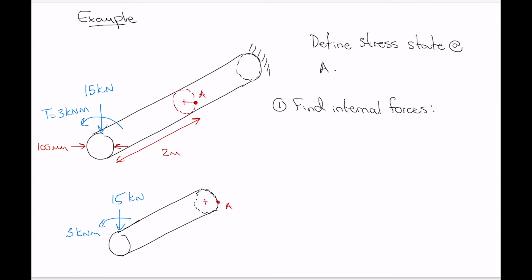So the easiest way that I personally find to do this is, first of all, take your coordinate system, and we don't have one laid out yet, so we want an overall coordinate system for our object here. But I'm going to position it right on the centroid, with its origin on the centroid of the section cut that we've made here.